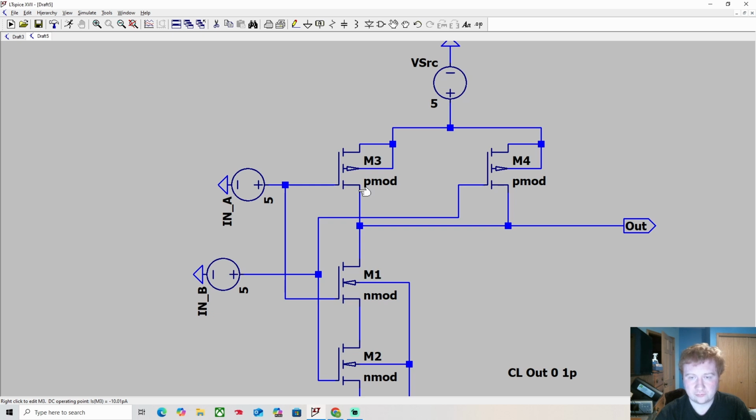So anyway, with MOSFETs, with these high side configurations on the positive MOSFETs, if the source voltage connected to the source of the MOSFET is equal to the gate voltage, the MOSFET will not conduct. It'll basically shut it off, acting as a normally open switch.